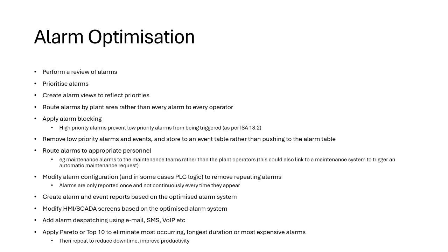For example, consider that tank level. We've set the alarm limit at 90%. The alarm might be going off every 90%, but the actual level might be rippling between 91 and 89%. So every time it goes from 89 to 90 and then above, the alarm is triggered, but actually it's only one alarm, but because of that ripple or oscillation, we could see that alarm is repeating.